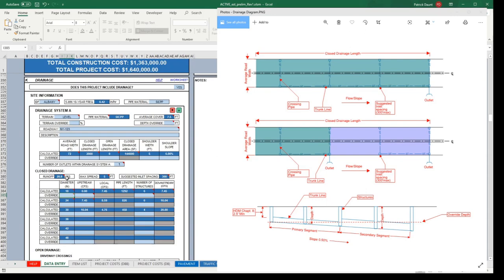You can adjust these diameters later in the backup to whatever value you'd like, but for this hydraulic analysis and for the very preliminary data entry tab, we're just going to stick with the smallest value of 18 inches. So if you select maybe a 24 inch, and I know there's an 18 inch pipe upstream, we'll start with the 24 as the first proposed pipe.